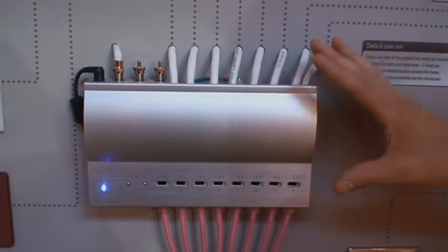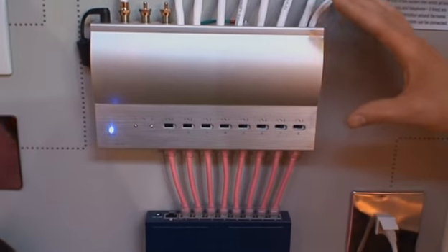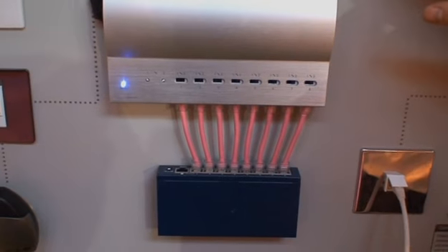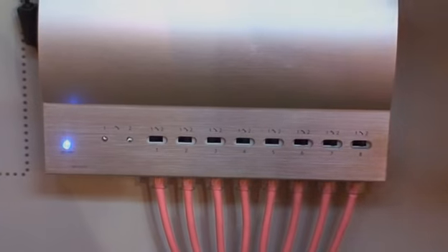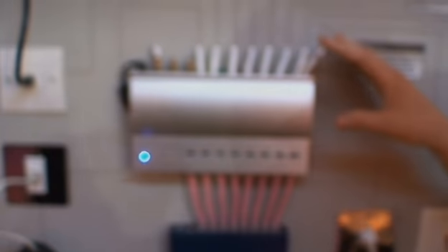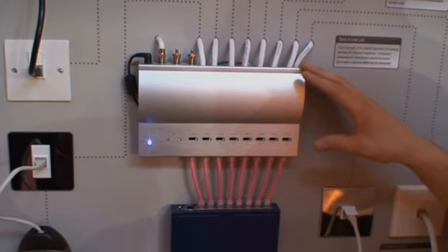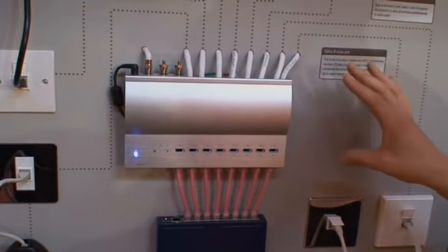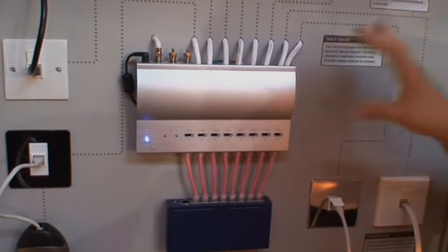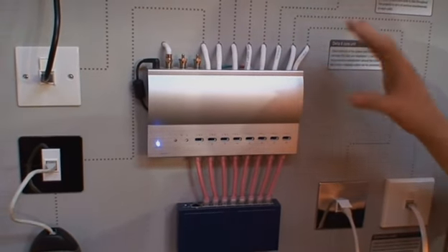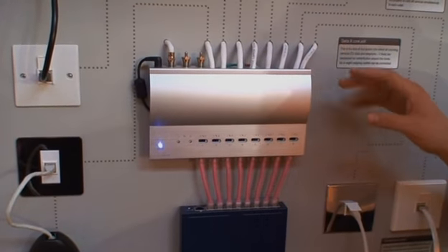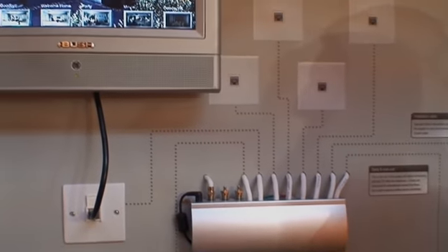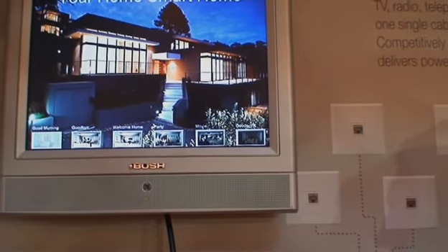With the Delta 8 unit, we don't actually include modulated signals. So as a standard, you get your integrated Freeview pictures, and you also get your standard analog signals. It's down to installers if they want to add in modulated signals, but as a standard, we don't include that because this unit unfortunately doesn't have IR control paths. So as an introduction to the marketplace, this is a very competitive product, and hopefully for an installer, it should make it easy to install because instead of 3 cable services, we only have 1 cable and less time on site.